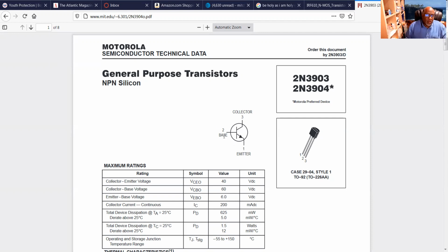So, for example, if I have an ohm meter and I put the positive terminal here and the negative terminal here, I'll actually get current flowing in this direction, which means I know this is P and this is N because this is a diode junction. So this would be P and this would be N. Now the question is, if I put positive here and negative here, this is also a PN junction. There's a diode junction here also. So how do you know which one is which?